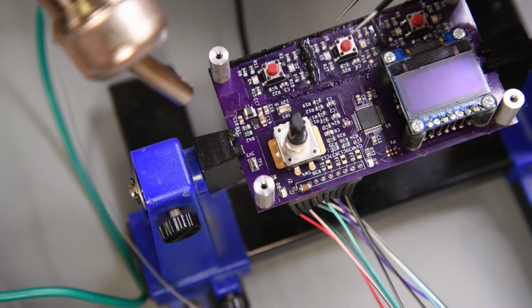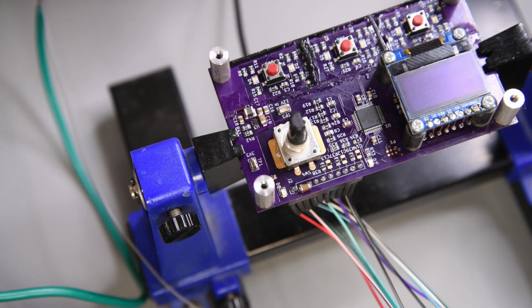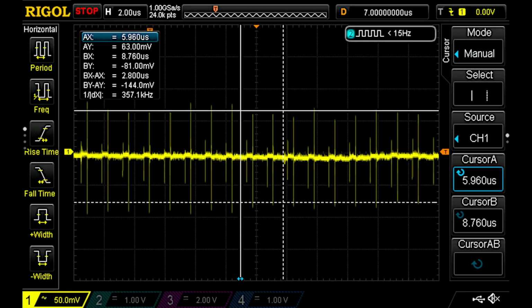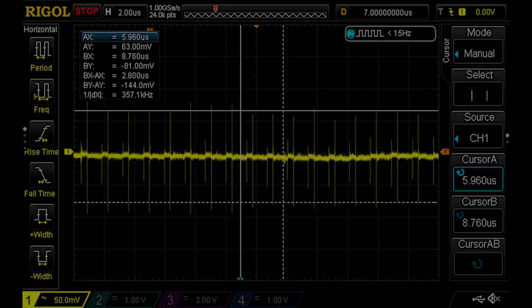Even though these are 50 volt caps, with 12 volts on them, it still takes 2 to get me to 10 microfarad. And now the 12 volt rail, right at the regulator, looks like this. The very thin spikes, I suspect may be noise picked up by the scope probe, and not really on the 12 volt rail. But the voltage ripple is less than, say, 20 millivolts now. I think I could have gotten away with just the one 10 microfarad cap. But I'm hunting noise and quashing, and I think I've got one noise source under control now.